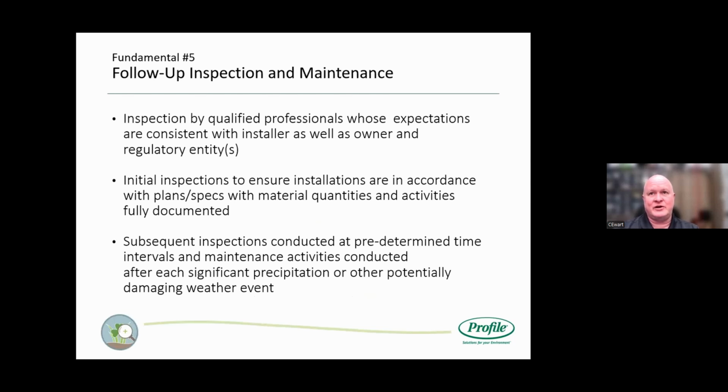Suggest having somebody who knows what they're looking at go look at it rather than just dispatching anybody. Might seem like a no-brainer, but I have seen many times where they send somebody who's brand new to go inspect the sites. They don't know what they're looking at, and they may miss problems or potential problems. Make sure that it matches what the plans say.